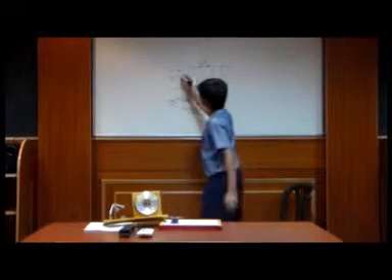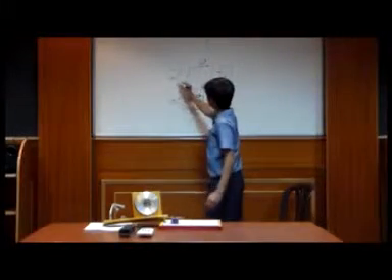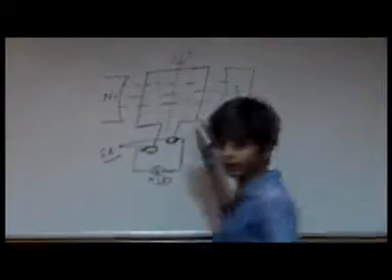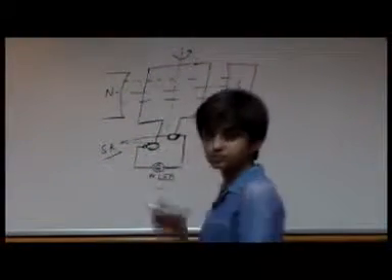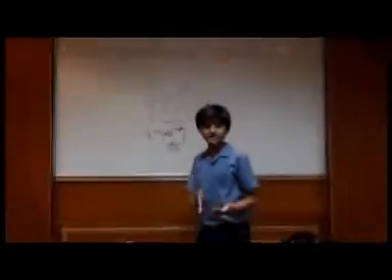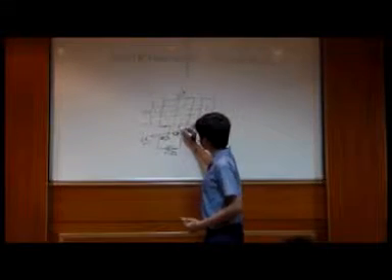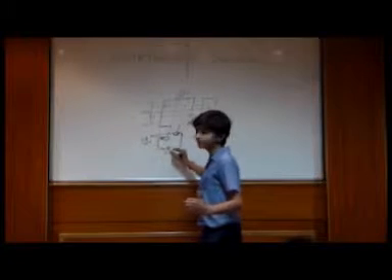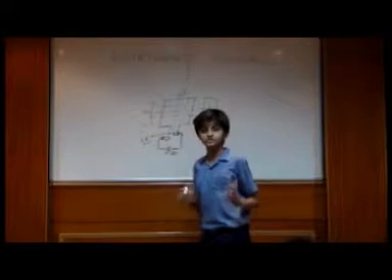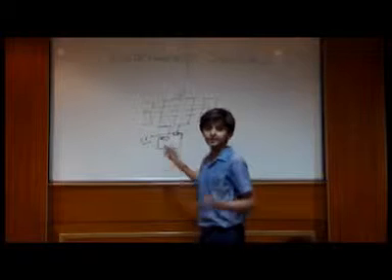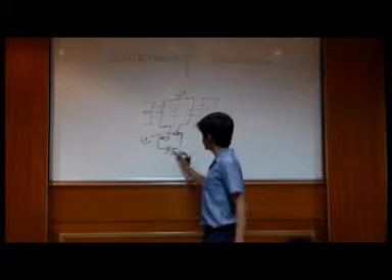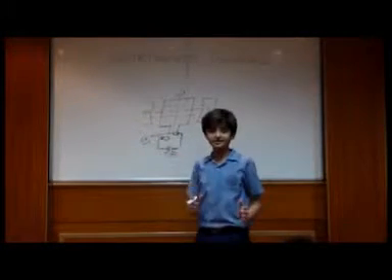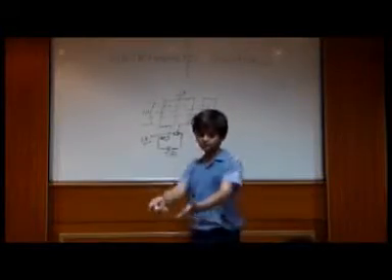When this rotates, there are magnetic field lines between the two poles of the magnet, the north and south poles. When this coil rotates, the magnetic field lines are cut. Because of that, current is induced, and it passes through these wires and comes to the galvanometer, which shows the reading and presence of current. The galvanometer can also be replaced by an LED, which in turn glows, as you can see in this model.